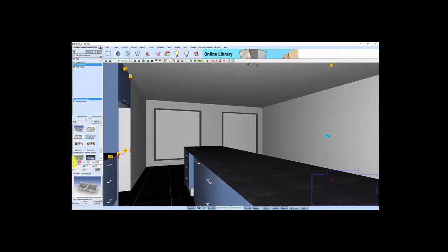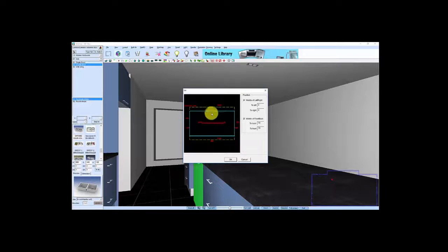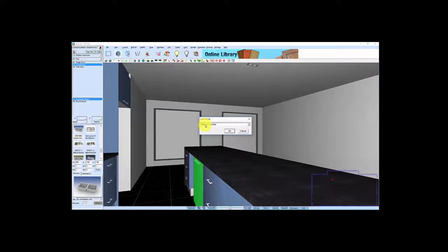The width of my sink, I'm just going to change that to 800. Press layout, press the cupboard that I want it to go onto. The sink is larger than the unit, the worktop may not be created correctly. Just go yes, because I know it will. Again, you see the blue line is the sink and the yellow line is the cabinet. Okay, and we just go okay. I know I don't want the sink over the worktop, I want to go under, so I want to go under worktop. So we go okay. We go okay.